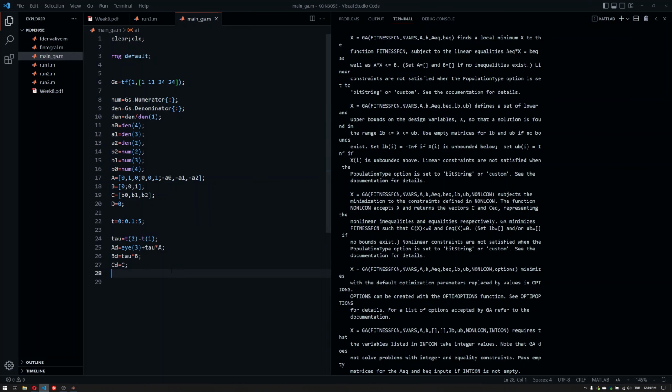So, what is our x vector? Well, our x vector is going to be the following. Let's call it kp, ki, and kd. So that's going to be our x variable here. Now, therefore, let me generate the lower bound for them. Maybe I want to work with only 0 values here, so zeros and 1 by 3. Let's put in an upper bound. Let's have 500 so that we don't end up in very big numbers. 1 by 3, ones(1,3). So yeah.